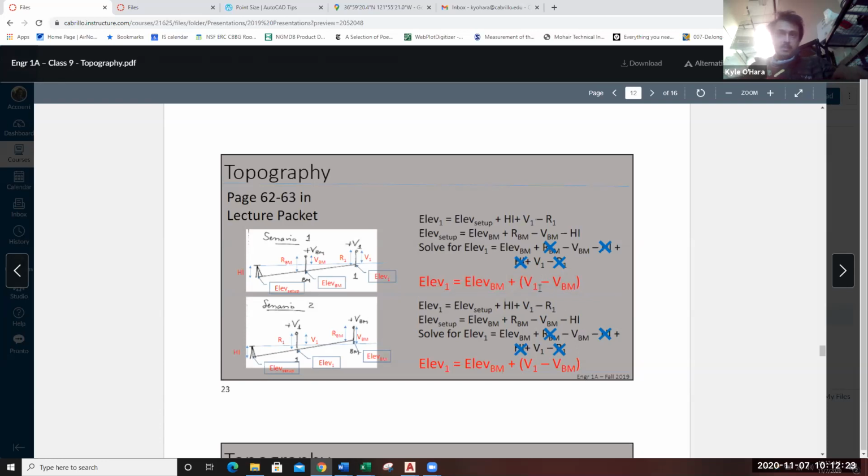So for our total station readings, the benchmark, we're just going to take that once at the very beginning of our survey. We're going to do a backsite to our benchmark, figure out that vertical distance, and then we're going to have our rod person take our prism and walk around all of the important points, capturing all of our elevation changes.